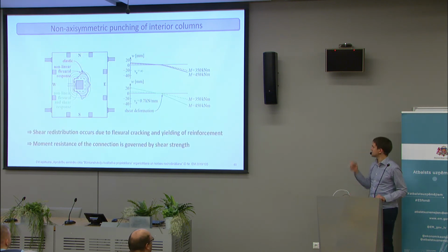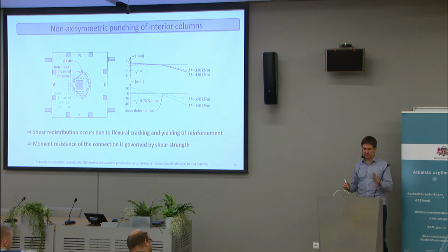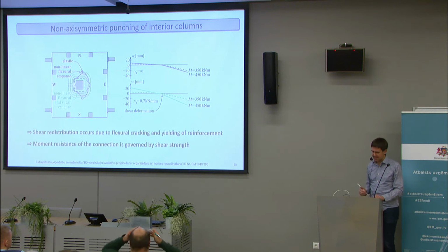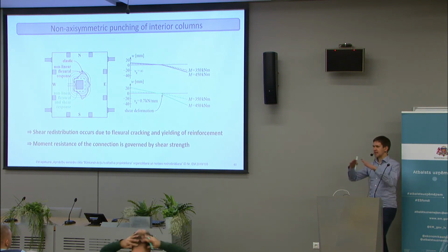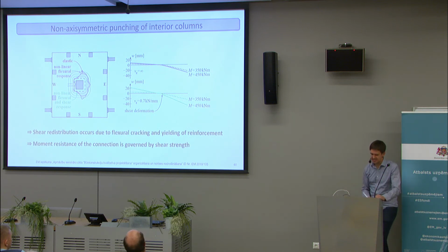And then I looked at the shear distribution, the distribution of shear stresses on the control perimeter, to see what's the influence of this shear plateau, or limiting the shear stress. The red line in here shows the elastic distribution. So this is pretty much like the American distribution. This means elastic in the flexural sense, that the bending response is perfectly elastic.